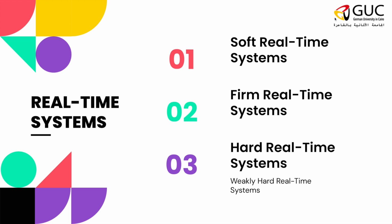So instead of having one deadline to meet, which if you did not meet, you will die, we implement redundancy. So you'll have, for example, a full braking system that consists of 3 deadlines. And you need to meet at least 2 out of the 3, or for example, 1 out of the 3, for the car to brake. So this transformed the car brakes from a hard real-time system, where you need to meet all of your deadlines, to a weakly hard real-time system, where meeting one or multiple deadlines out of the total deadlines will make you safe and will keep you safe.